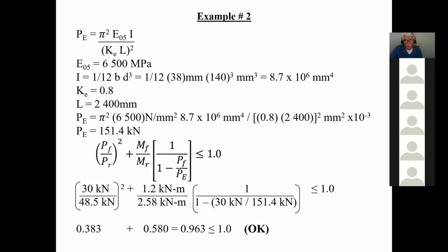in real life, if I'm doing this interaction equation, okay, you'll see this when we do the exterior columns in steel. Like this interaction equation, what you have to understand is that let's say I chose a 2x6, okay, fair enough. And all of a sudden I get the sum of these two ratios, I end up getting 0.43, less than 1, okay. There's a very good chance that I can get away with a 2x4, so I'll check it with a 2x4. You follow? You can get away.